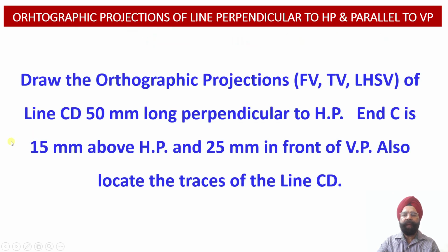Here we are required to evaluate the orthographic projections of a line which happens to be perpendicular to HP and parallel to the vertical plane. Now the line CD is 50 millimeter long and it is perpendicular to the horizontal plane and parallel to the vertical plane. So we are required to draw the front view, top view and the left hand side view projections of this particular line CD, and we are also required to locate the traces of the line CD, that is horizontal trace